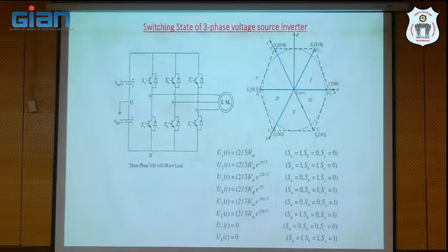We can improve the performance of the electric drive, right? Whenever you want to control the flux, or whenever you want to change the state of the torque, the essential thing is you should know where the actual flux position is, right? What is the length of the flux? You should know what torque is generated by the machine. If you know, we can easily identify.